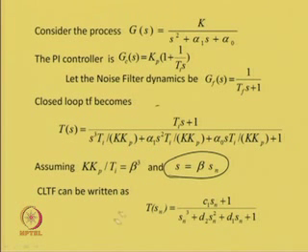Now, like the earlier case, with the help of simplification, it is not difficult to find explicit expressions for the two unknowns of the controller, Kp and Ti. And since we have Tf equal to Ti, there is need for estimating only two unknowns for the controller. Kp and Ti are the two unknowns, then all other things are known and the closed loop system will have a controller in place.